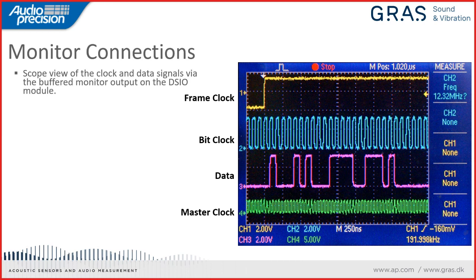And if all three of those coincide, life is good and everything will work. And if one of those does not coincide, I'll troubleshoot that problem. I may have the device under test misconfigured. I may have the APX misconfigured. I might have a physical problem as well. But in this particular screenshot, this is exactly what you can see if you connect the monitor ports to your oscilloscope.